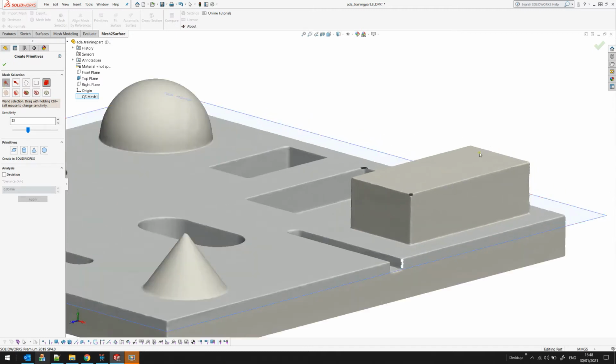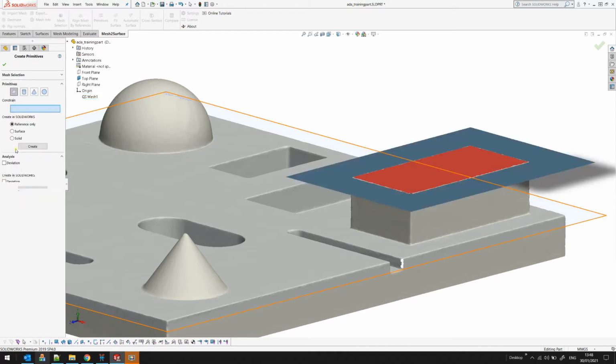I'll use my selection tools and click on the mesh, and the software automatically will select based on the curvature. Next step I need to do is just press on the icon which is for fit a best plane. What happens now is that the software uses algorithms to find the best fit through the points that belong to the selected triangles. You can see the result on the screen shaded as a plane.